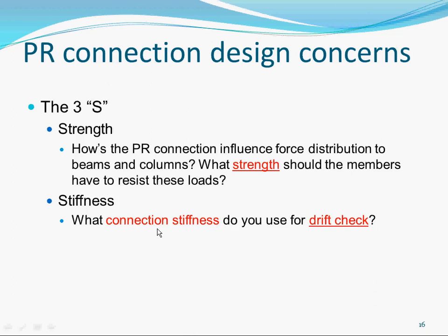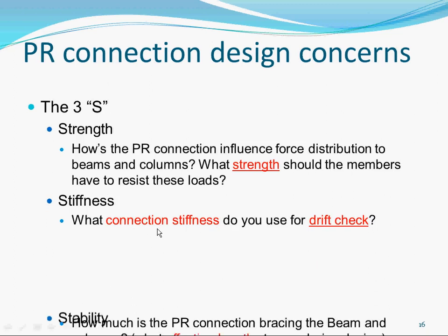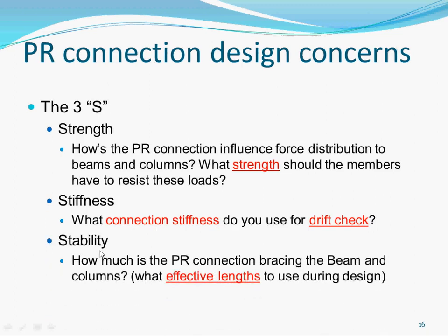Stiffness. What connection stiffness do you use for drift check? And stability. Stability is related to what effective length to use during design for your beams and columns. So let's see how we address some of these in our connection.